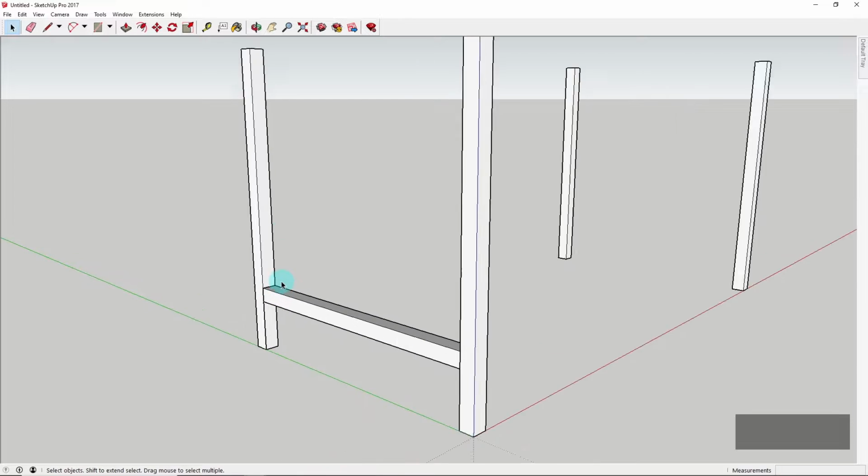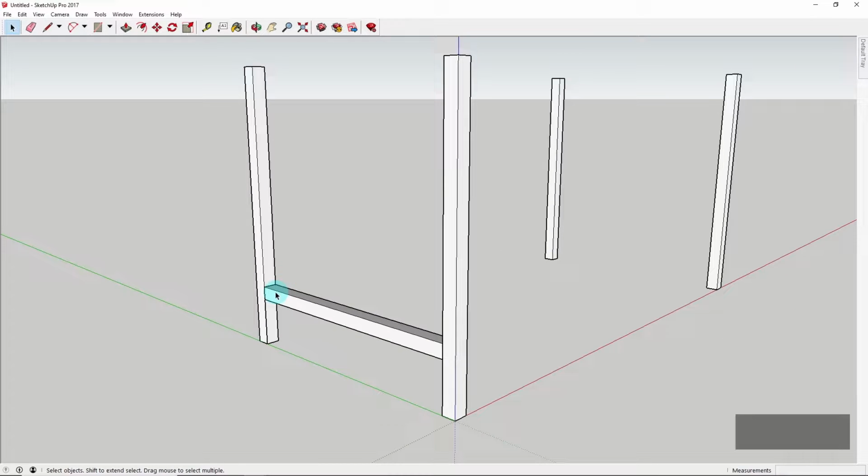And so from this point we're going to move it. So we're going to click on the shape we want to move, hit the M key on our keyboard, grab the point we want to move it from, so this end point, and we're going to move it along to this side, press Control on the keyboard. And as you can see, it's not necessarily locking to the red axis as well as I'd hoped. So what you can do is, whilst you're moving your object, if you click on the arrow keys, you'll see